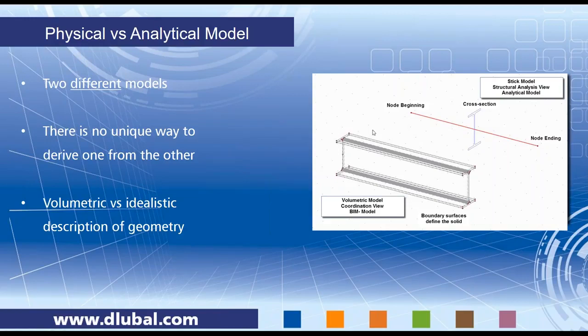What we see below here is what we would also get in the so-called IFC coordination view. So we get a volumetric model, and this above would be the IFC structural analysis view. These are two different models, and IFC does not necessarily take care of the transition from one model to the other. So this has to be done either in the BIM software or afterwards in the structural analysis software.